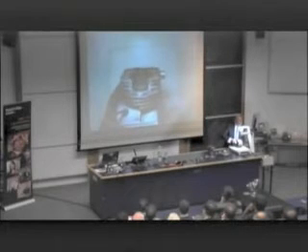So an engine will go, piston will go down. Piston will go up. Now just to get it to the right place, which must be here. The audience will tell me otherwise, I suspect. Yeah. So that valve, blue, is now lifted, you can see it. So air will come in. So it's open, it's coming into the cylinder, it's filling this space here, but of course